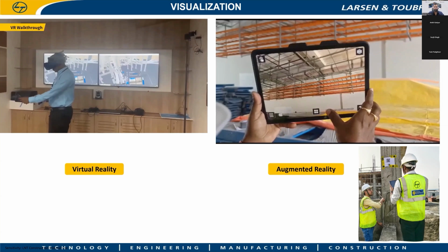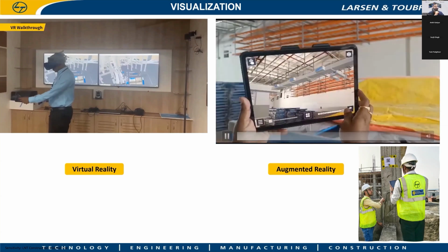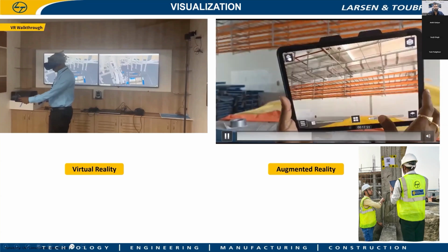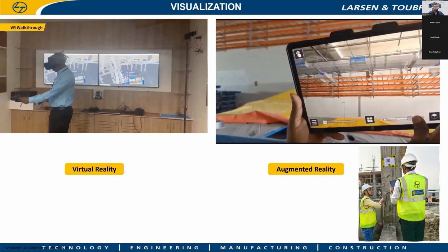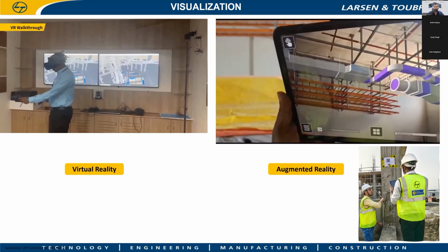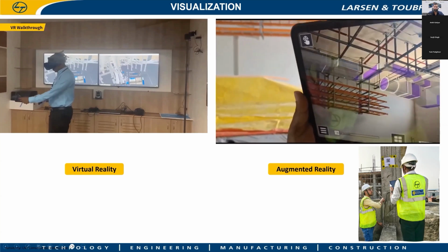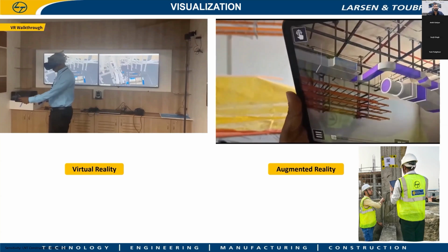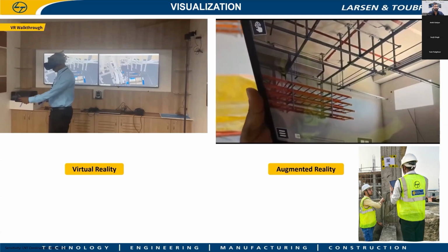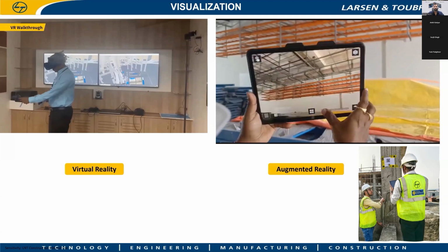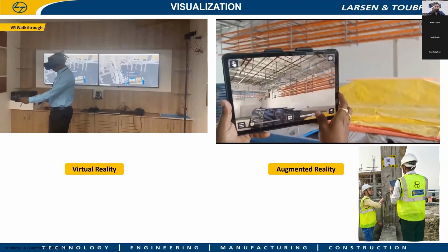Nice. Which software tool do you use for this? We use Trimble Connect currently for deploying AR, but we use various platforms across various projects at site. Also, to ensure the column positions and rebar spacings, all those things, we can ensure whether the actual site condition is aligned with your design through the AR platform. Great.